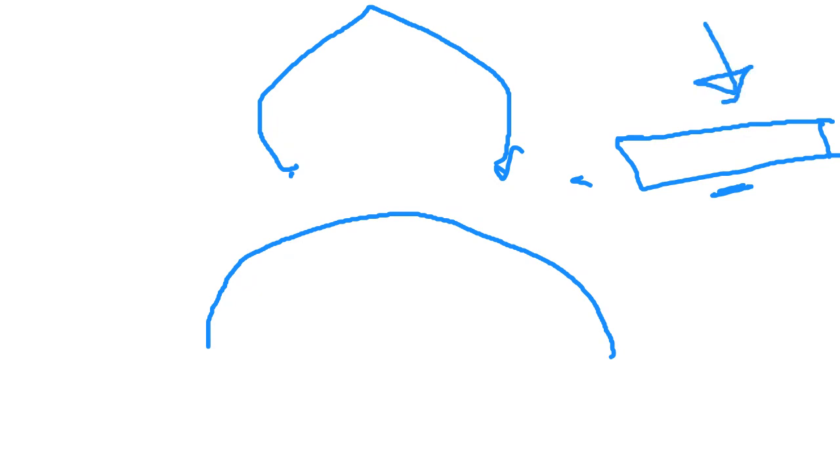inside the wall. So even if you see any old structures, the purpose is to give such shape, because if you use a flat beam, what is going to happen? The bottom part will be in tension, right? And the top part will be in compression if we apply load vertically at the top, right? So what we use is, whatever the moment shape, if you draw a bending moment diagram of any such beams, like this, I'm just drawing for a UDL which is in this shape, and you just reverse it, right? Just try to reverse this diagram.